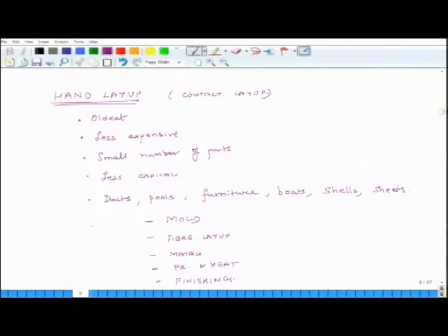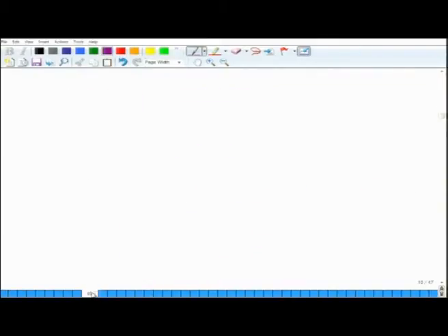Okay. So, this is the overall process, fiber layup. So, this fiber layup, putting matrix, all this is manual. Okay. It is not automated. So, we will discuss this further, but before that I wanted to put some important comments about mold making. So, this is the first step, this is second step, matrix placement is third, application of pressure and heat, and we are finally finishing. So, we will discuss maybe for a couple of minutes some more detail about mold making.